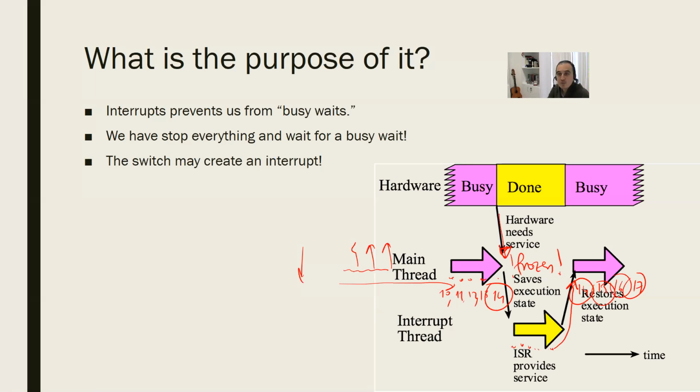When in subroutines, you jump to a subroutine, right? But subroutine jumps are initiated with instructions like BL sub1. Well, this is initiated by code, but in line 14, we don't have something like that. It automatically jumps whatever the instruction at line 14 is. So it is not related to the instruction. Remember, guys, jumping to a subroutine is related to the instruction because the instruction tells us to jump to the subroutine.